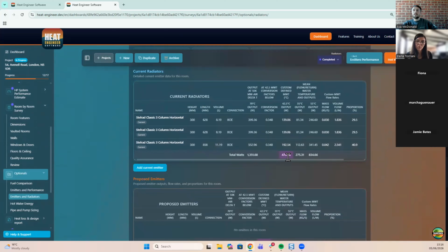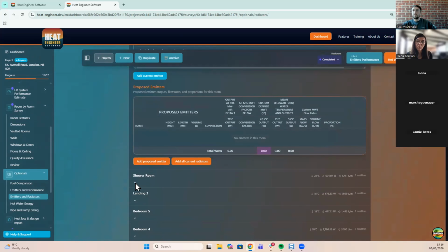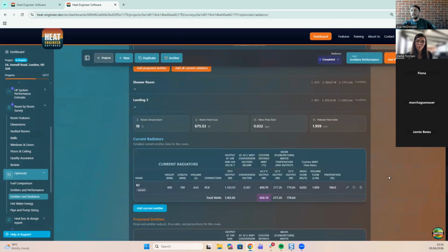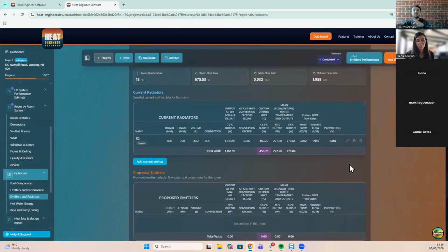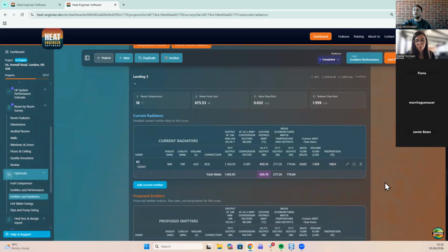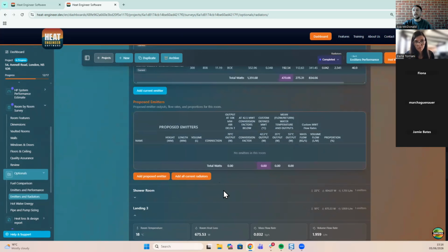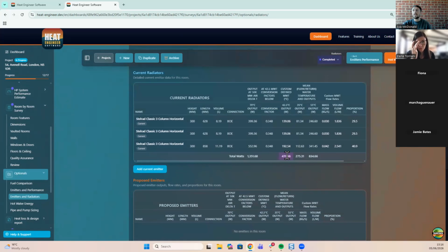And that's the consistent theme, because ultimately we're lowering the flow temperature and the radiators currently are working at 70-degree flow and a delta T of 50. So target room temperature 20, flow temperature from the appliance 70, and that's what gives you the delta T of 50. So what we can do in that instance, we've obviously recognised there that we need to upgrade our radiators.